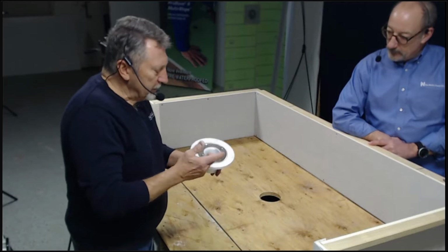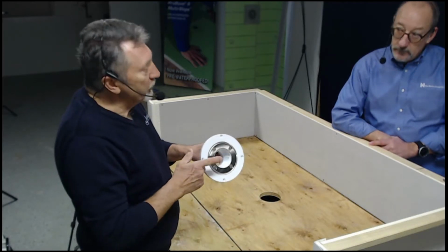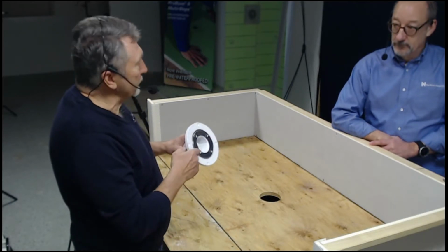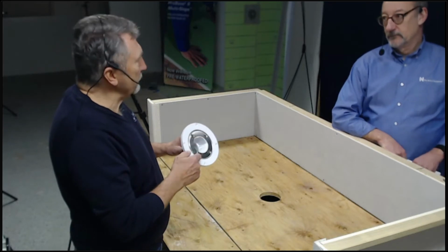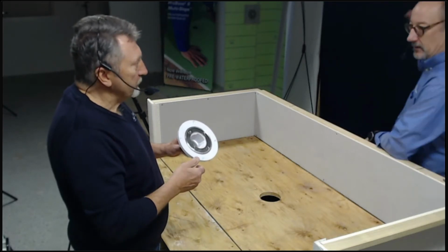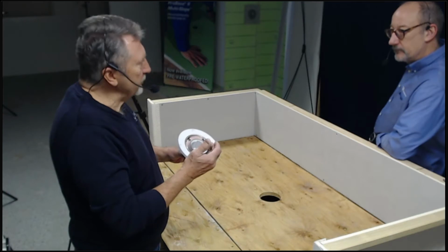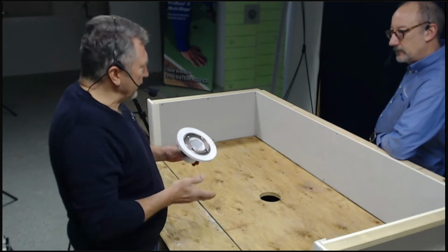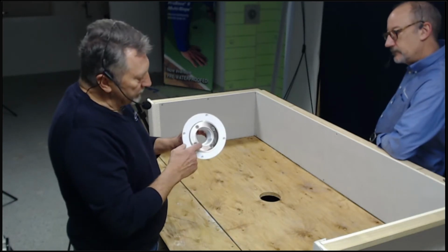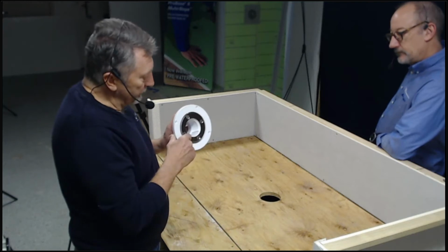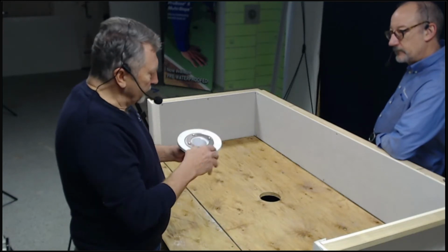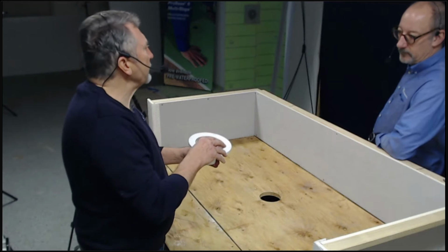It has a clamping ring. We know in the industry that a clamping ring is a bulletproof seal between your membrane and your drain. Gives it that tight connection. It does. Not only are we going to chemically seal it, but we're also going to mechanically seal it. It has internal weep, so you don't have to worry about any of the weep protection and go around that at all.